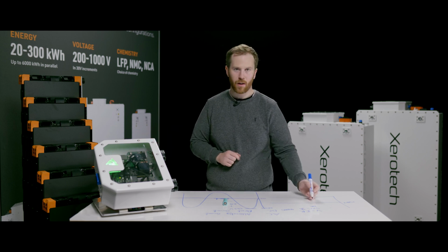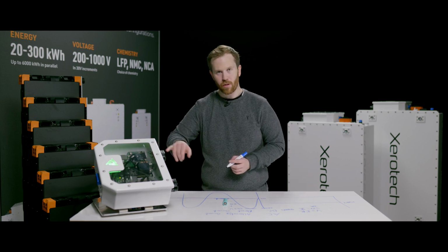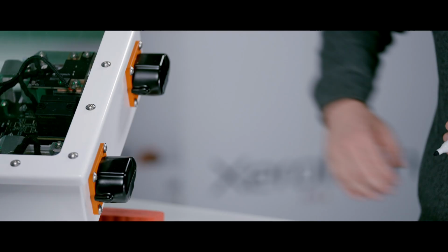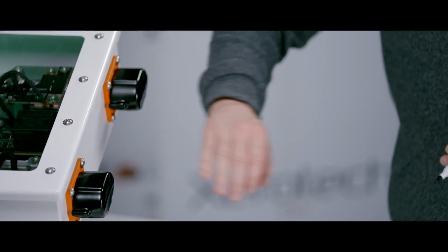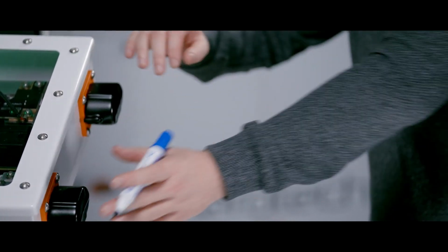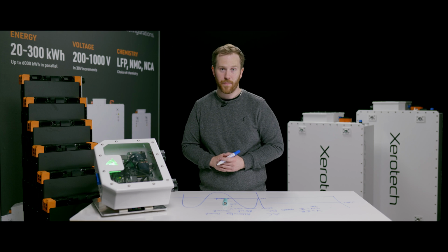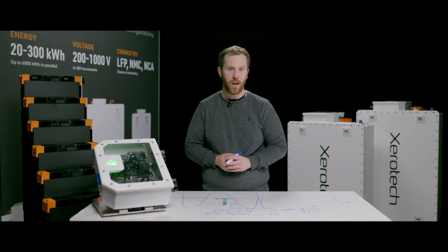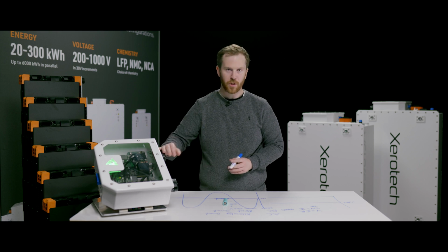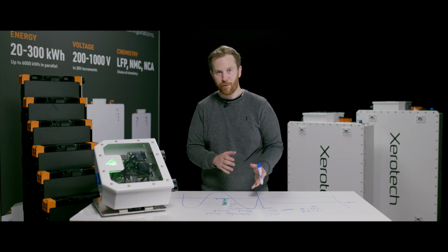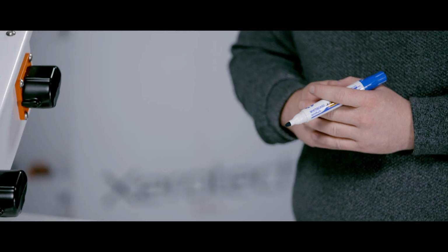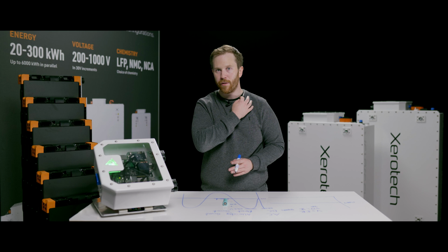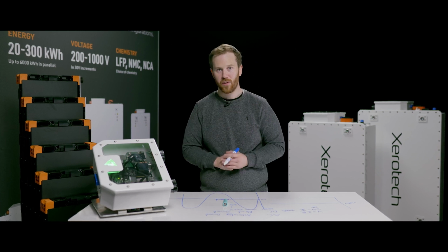Batteries are floating, and what that means is the negative or the positive, they're not referenced to ground. I'm standing on the ground. So if I touch positive, nothing happens. If I touch negative, nothing happens. If I touch both, I'm going to have a very bad day. So that's the big difference here when it comes to DC systems. And when it comes to safety, voltage is potential difference, the difference between two surfaces. So if you haven't completed the circuit, then you're going to be safe. That's totally different to alternating current that we use today.